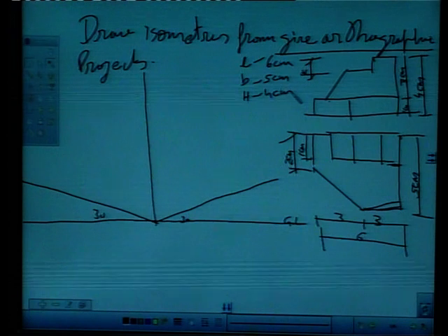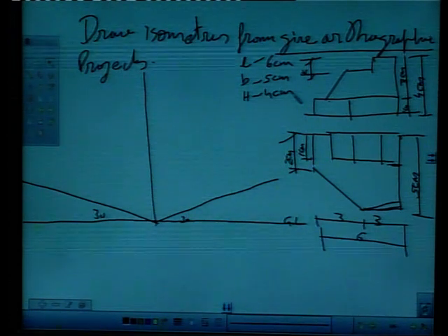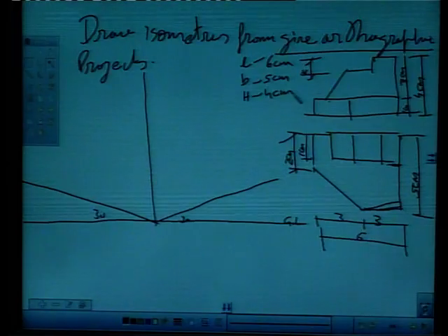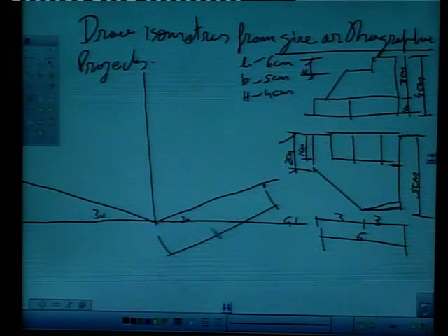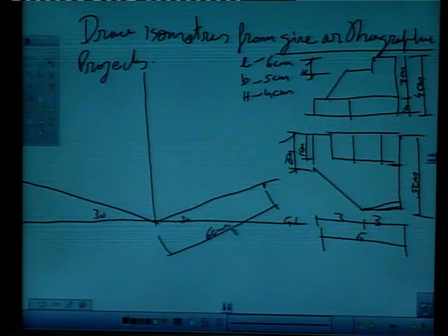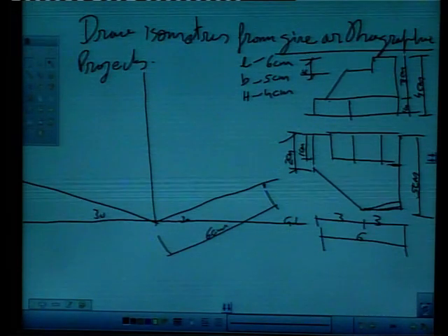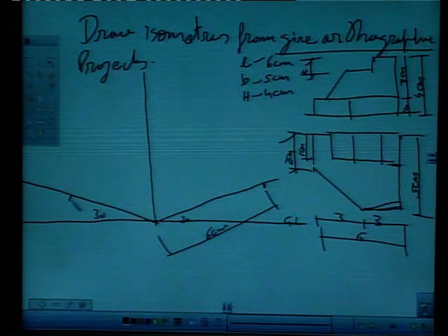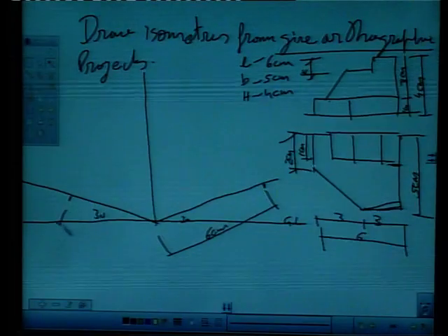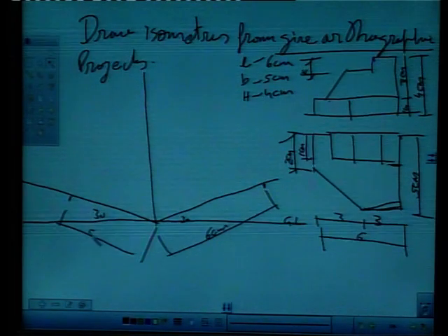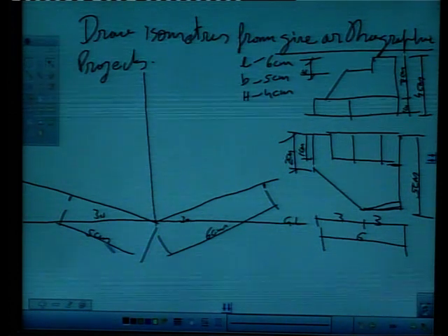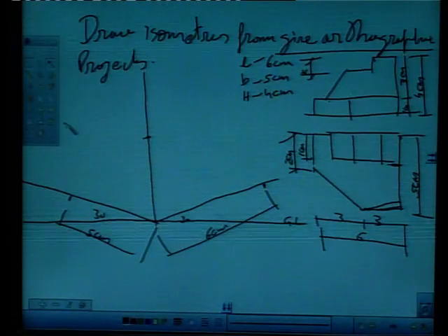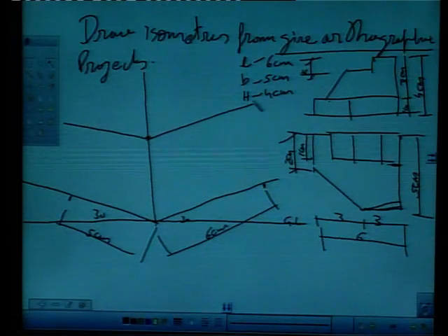So what we will do is, first of all we will make a cuboid with these maximum dimensions, right. Say this is 6 from here to here, right, 6 centimeter. Initially we draw everything in guidelines only, right, and say breadth is 5 centimeter, mark breadth on left, right, say this is 5 centimeter here, height is 4 centimeter, mark 4 centimeter on height line and complete the cuboid in guidelines only.